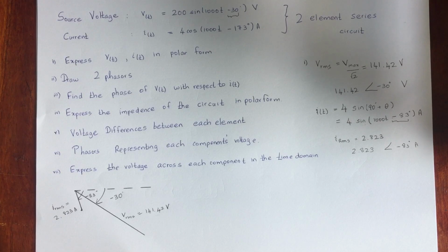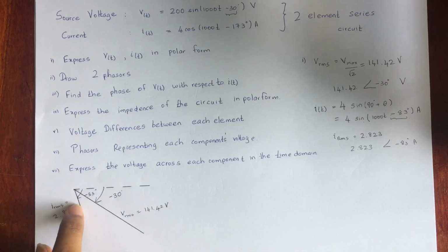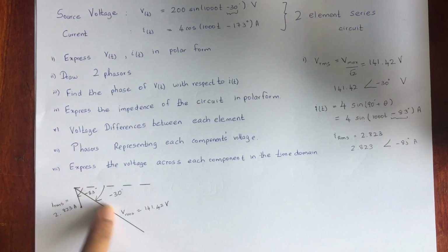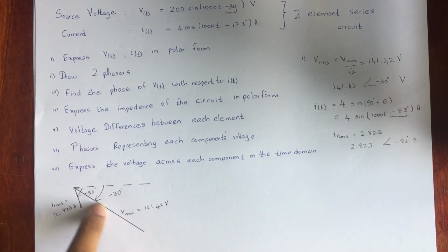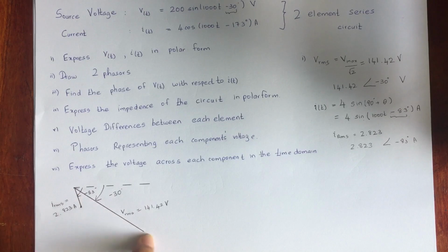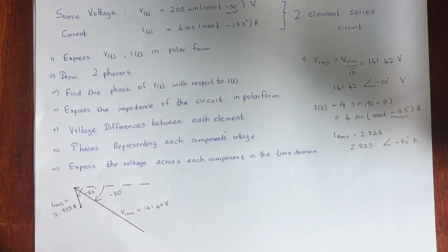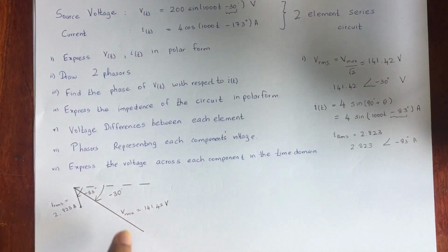So the thing here is whether this is the only phasor diagram you can draw for these two phases. No, you can draw in many ways. Let's say you can take the voltage as a reference line and draw the voltage line in a straight line. If we take the voltage as the reference line, this I would be 53 degrees downwards, or in the clockwise direction from this voltage.